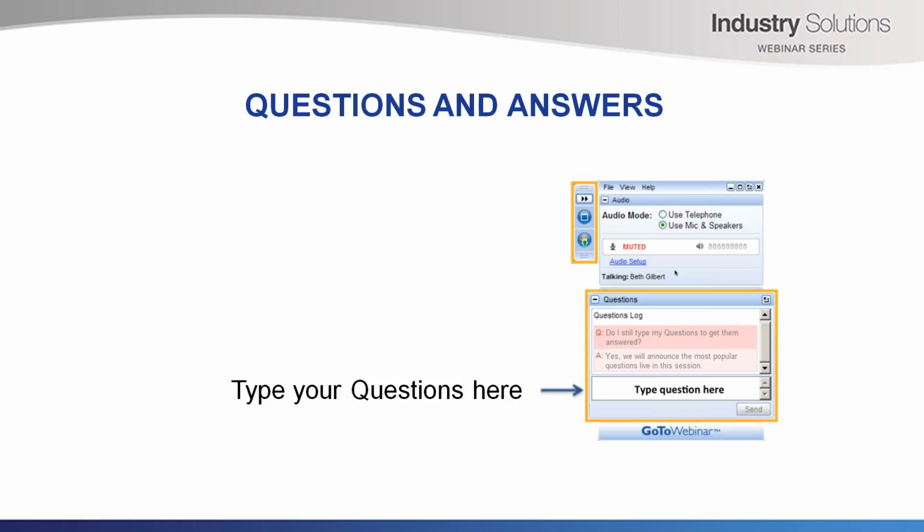The attribute manipulator allows you to create string or trimesh or tin attributes for a lot of those properties. And then when you write them out, they'll go out to IFC property sets and be there at the other end. You just have to find out from the person who wants the data what they want those attributes to be called and exactly what they are. They might say length. Is it 2D length or a 3D length? You know, little questions like that.